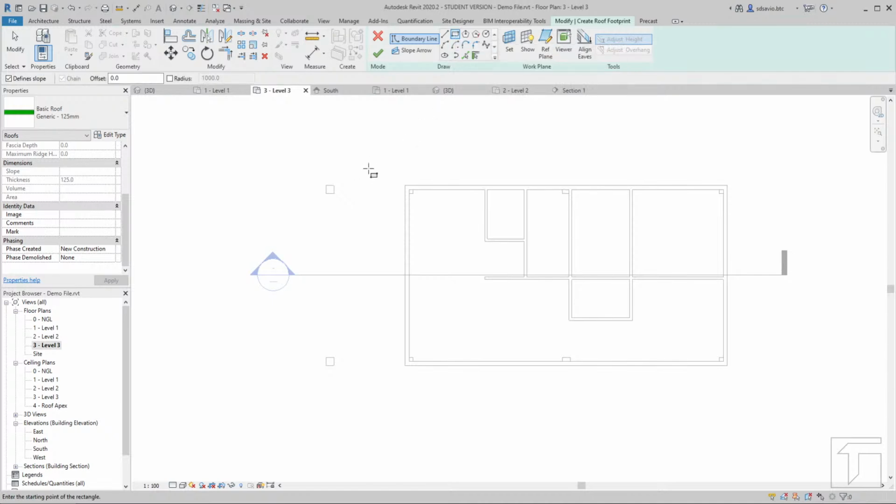And then afterwards, since normally roofs have eaves, right? The standard is about 600 millimeters. So to instantly draw the eaves, or rather the extension of 600 millimeters of the roof, we will now add an offset to that. On the options bar, we have the offset. Let me type there 600, and that should offset instantly by 600. So if I click on the corner of this column, notice that it offsets automatically the guideline of the sketch by 600.